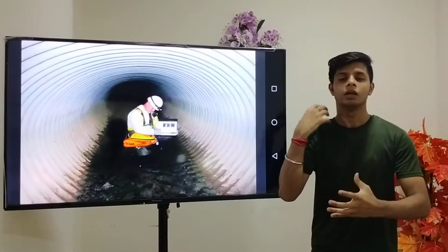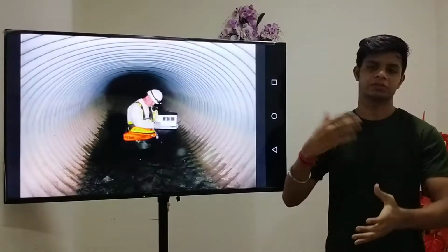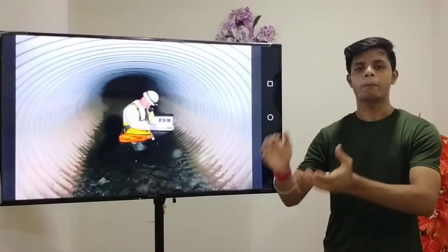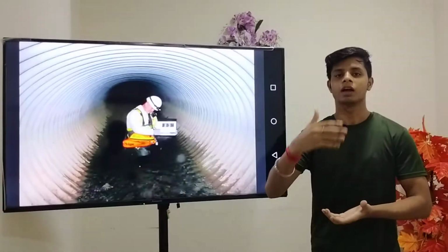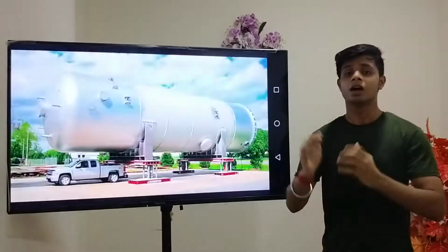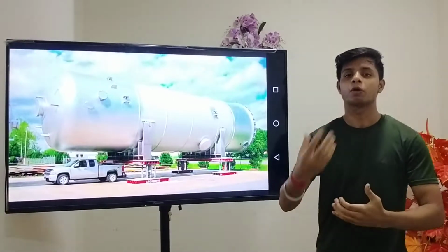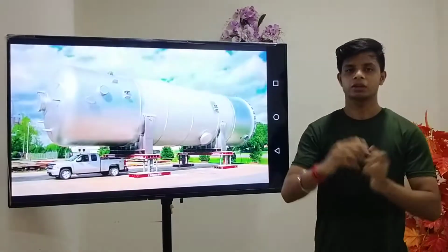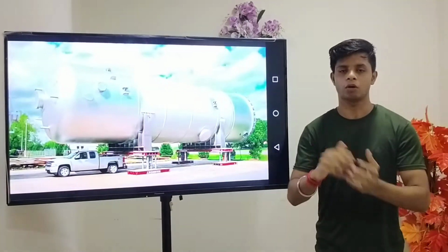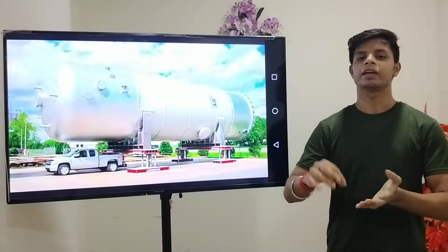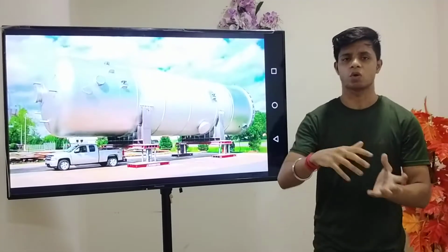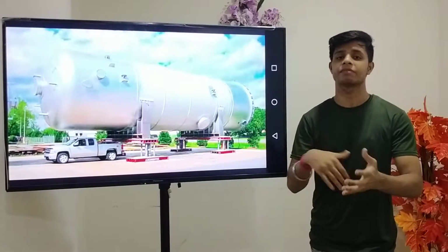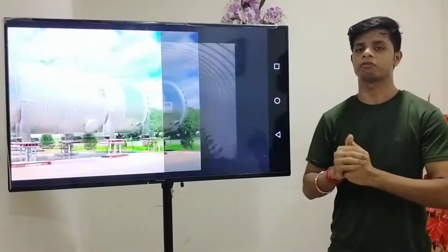If it is not, you need to go with engineering controls and administrative controls, with the addition of PPEs. Third, you need to appoint a hole watcher, or you can say a confined space attendant. The use of that is, whenever you are going inside, he will be checking whether you are okay or not. If not, he can contact the emergency teams. After that, you need to maintain a confined space log sheet. In the log sheet they will record who are the persons going inside, for what time duration they are going inside, and at regular intervals they will check the O2 levels inside the confined space and all.